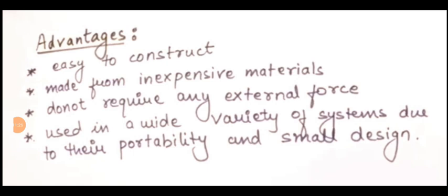The construction of the rotameter is very easy, and that's why rotameters are widely used. It is easy to construct and made from inexpensive material. It does not require any external source. Here we are not using any external source; the rotameter works due to the gravity and buoyancy forces acting.